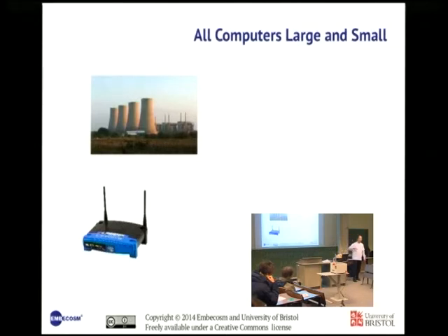That's why, actually, in this area, legislation matters. One of the things that came in a few years ago is the European Union started saying that standby currents had to be really low. Up until then, if you had a piece of equipment like your video player, when you put it on standby, all that it did was turn on a little red LED to tell you it was on standby. So it actually burned more power in standby because it had to power the LED. That's changed now. These days, when you turn things off, they will typically only use a handful of milliamps, not half an amp or an amp.